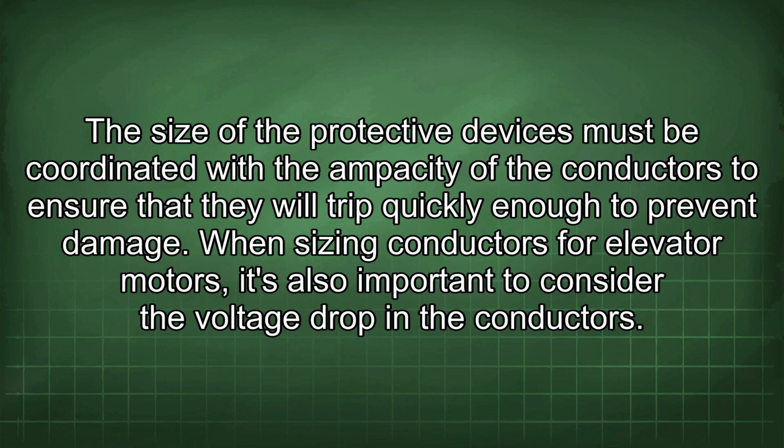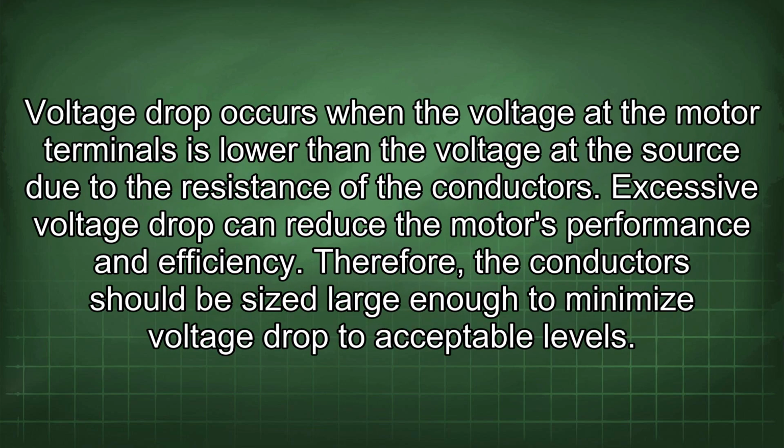When sizing conductors for elevator motors, it's also important to consider the voltage drop in the conductors. Voltage drop occurs when the voltage at the motor terminals is lower than the voltage at the source due to the resistance of the conductors. Excessive voltage drop can reduce the motor's performance and efficiency. Therefore, the conductors should be sized large enough to minimize voltage drop to acceptable levels.